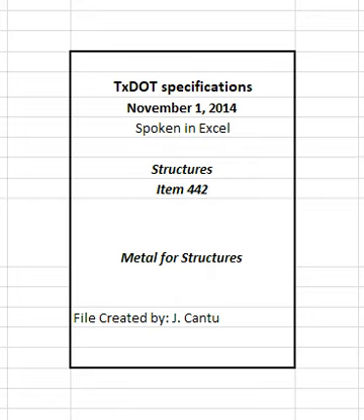If the requests for increases in sizes or weights of members are approved, measurement will be made on the sizes or weights shown on the plans. Castings, bearing plates, anchor bolts, drains, deck plates, armor and finger joints, and other metal for which no separate measurement is specified will be included in the total quantity of structural steel. The weights of rolled materials, such as structural shapes and plate, will be computed on the basis of nominal weights and dimensions using measurements shown on the plans. Deductions will not be made for material that is removed for copes, clips, planing, or weld preparation.